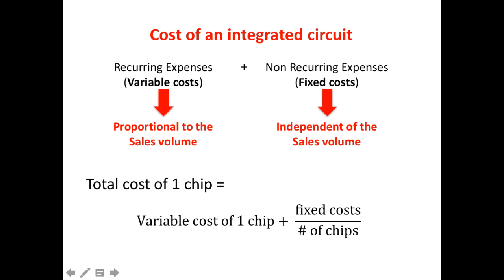The number of chips that you can do with the same embedded processor can be extremely high, so the fixed cost have a small impact. On the other hand, the variable cost per chip can be pretty high, because typically when you buy an embedded microprocessor, the cost of a single chip is much higher than the fabrication cost of a similar performing custom hardware.